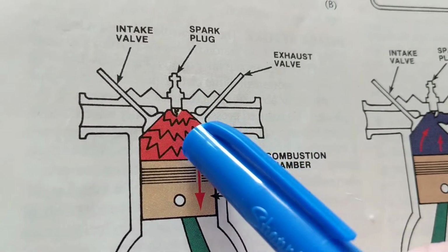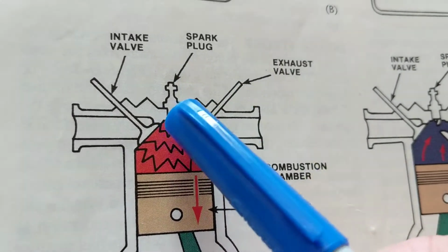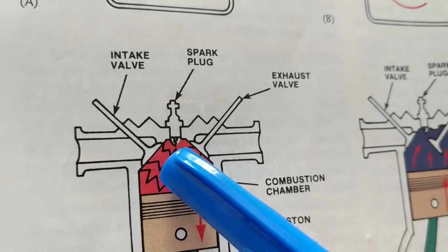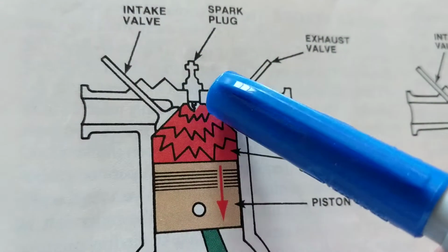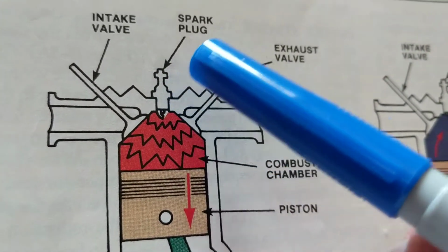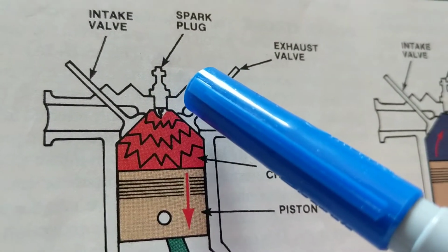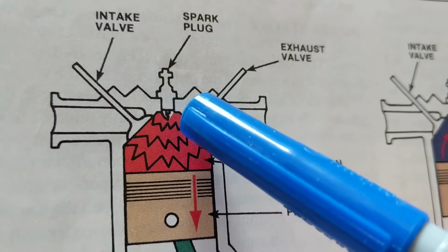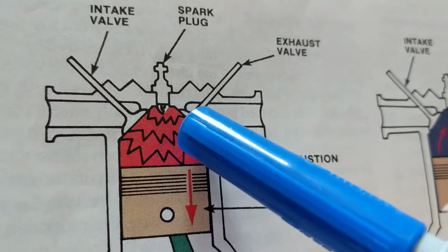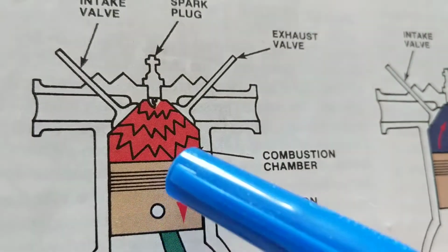When you come back up here, guess what? Now we have the air, we have the fuel, it's hot. It can reach about 1,500 to 2,000 degrees in there. That's as hot as it gets. We only need a little. Guess what happens then? The computer says, okay, fine. Spark time. It's time to spark. It's like lighting a match in this combustion chamber, where temperatures are high already and pressures are high already. We want that. Why? It'll force that piston down.